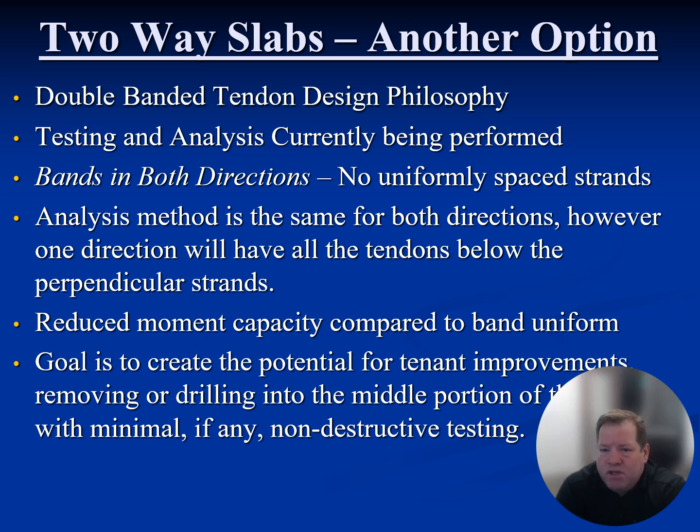So if you have an office building or a medical office building and you want to put in new equipment, but you don't want to x-ray the slab because you have to put in some quick bolts or epoxy bolts to anchor the machine down, if you know you have 20 feet by 20 feet in the middle of the structure of no PT, that's going to just make the tenant improvements easier. Conversely, if you want to add a stair, add an opening in the slab for some reason, again, if there's no PT, you're not going to break strands.